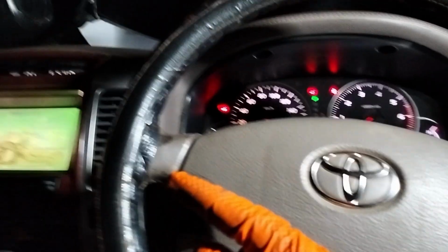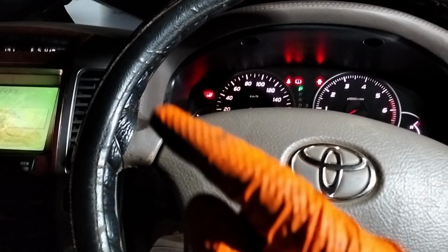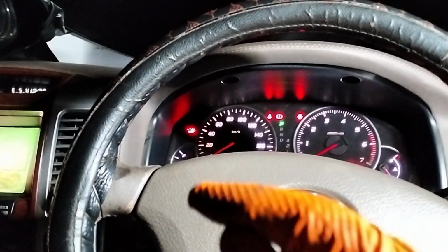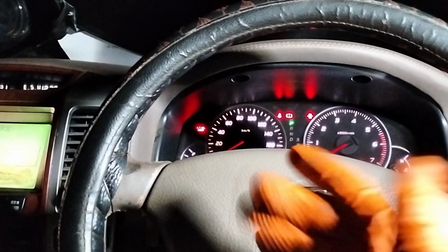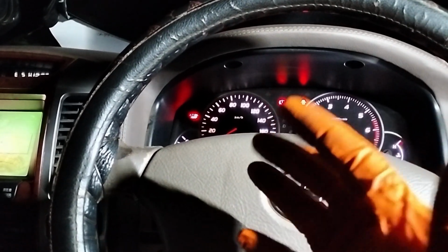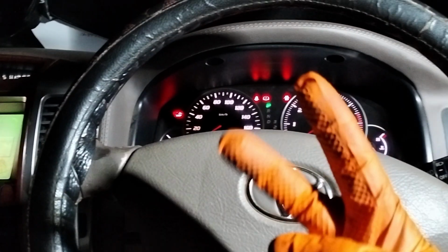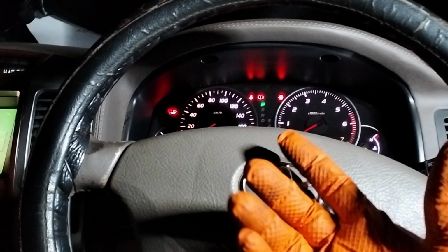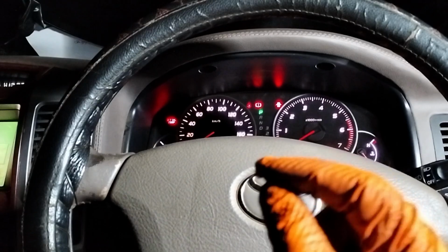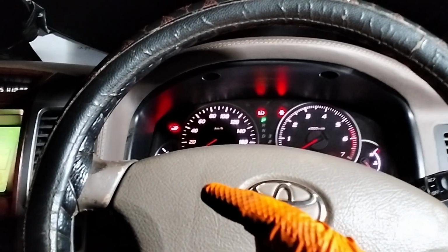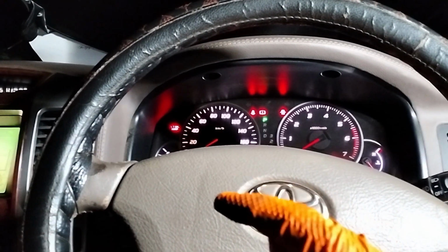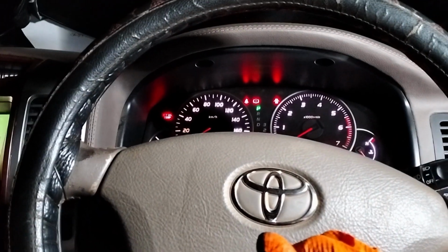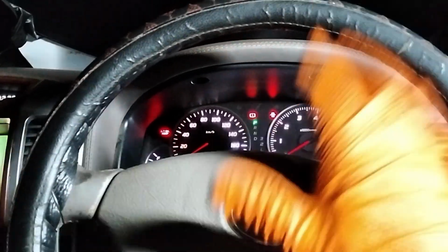After seeing that the part number of this motor that we took out was different, I am convinced that it doesn't have bad speed sensors. It simply doesn't have speed sensors. And another way I know that is there are 2 speed sensors in there. What's the likelihood that 2 speed sensors go out at the same time? Highly unlikely. The more plausible explanation is that part number doesn't have anti-pinch control and doesn't have the speed sensors. But they look exactly the same when you look at them physically. Well, that's it. Another one for the books.